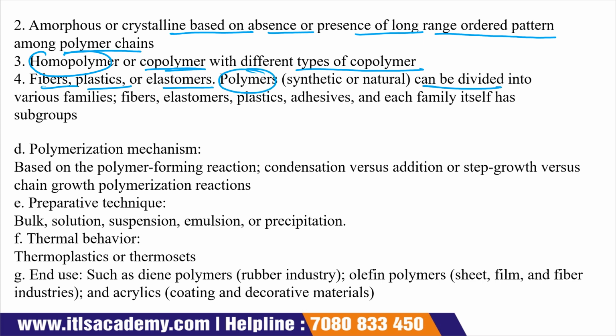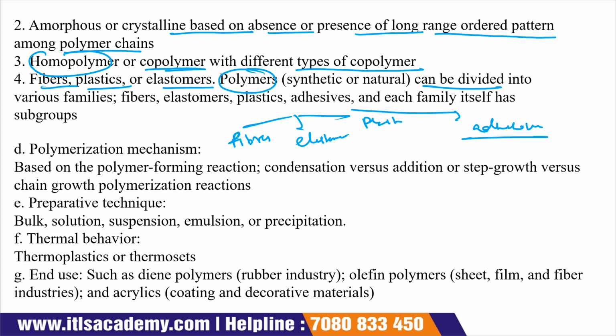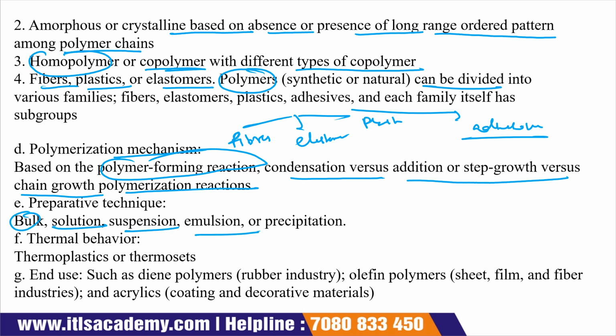Polymers can be divided into various families like fibers, elastomers, plastics, and adhesives. Then polymerization mechanism. It is based on the polymer forming reaction: condensation versus addition, or step growth versus chain growth polymerization reaction. Preparative technique like bulk, solution, suspension, emulsion, and precipitation. Thermal behavior: either they are thermoplastic or thermosets.